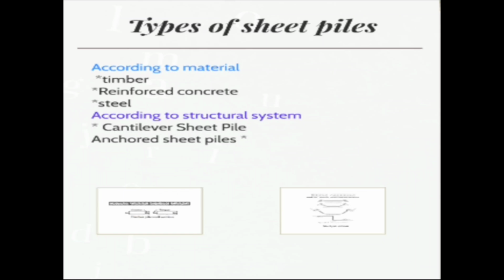And then, for steel sheet piling, these are long structural sections with a vertical interlocking system that creates a continuous wall. The walls are often used to retain either soil or water. The ability of a sheet pile section to perform is dependent upon its geometry and the soil it is driven into. So let's go on to the types of sheet piles according to the structural system.